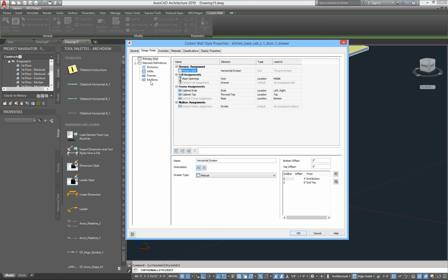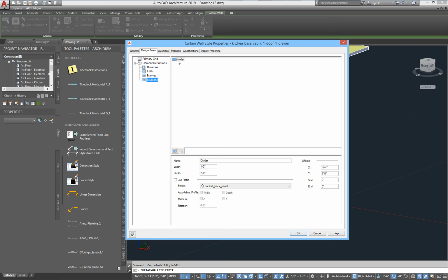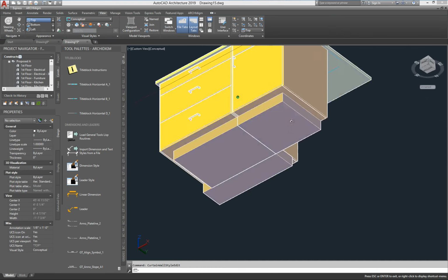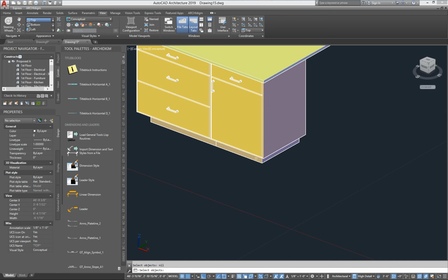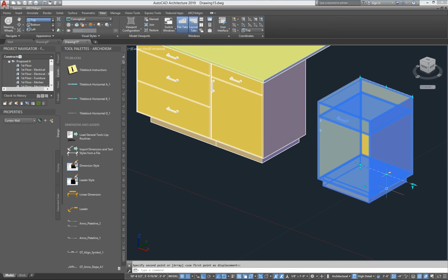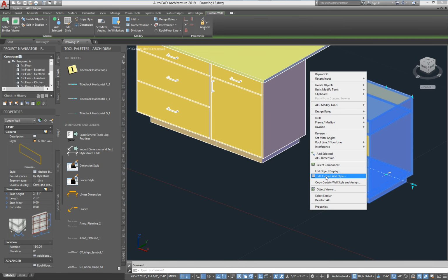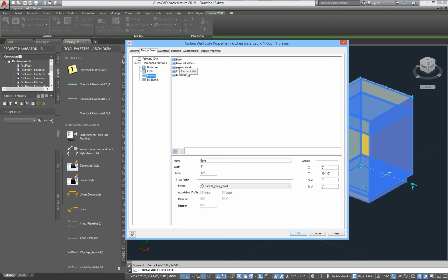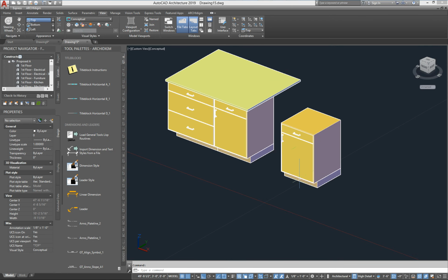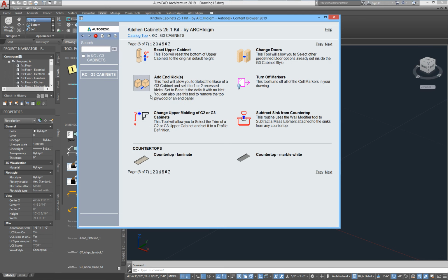So you go in and you go to, let's see, the divider, the frame. Here's the base. So as before, I could say 3. So this is 3, not 4, because this one doesn't have a splash on it. So you use the 3 inches there. But the problem is now, without an override on it, this cabinet will always have that. And if you change it back, it'll affect the other cabinet. So you might want to make a copy of the style with a kick on it. All right. Or you can use our tool here to just introduce an override.